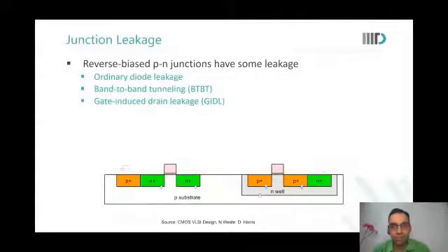Don't assume there is any current accumulation anywhere. KCL will still be followed. Yes, sir. There is no accumulation, but as you said, the device that can sink lowest current will now be the limiting factor. Since, as we stack transistors, the top transistors will become bad sinks, wouldn't that change my delays and all those things? When we move to the combinational logic design, we will see that there is a way to design around the delays due to stacks. We'll see that. That is called tapered design.